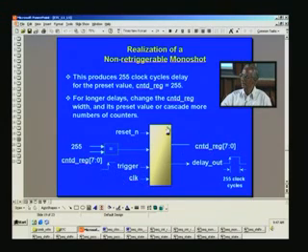Once again, all transactions take place at the positive edge of the clock, and when the counter register equals 255, this will be activated and this will be reset here, and that's how you get a delay of 255 seconds. And we'll see the waveform so as to get a better grasp.